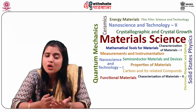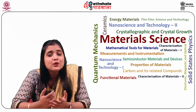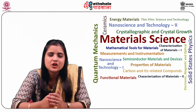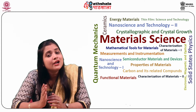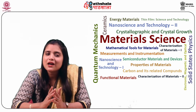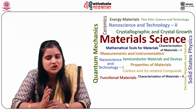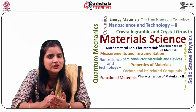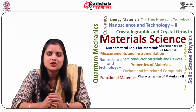The polarity of the Hall coefficient, that is, the sign of RH, gives an indication of the type of majority charge carrier in a semiconductor. That is, if RH is positive, the material shows p-type conductivity. Otherwise, if RH is negative, the material possesses n-type conductivity, having electrons as the majority charge carriers.